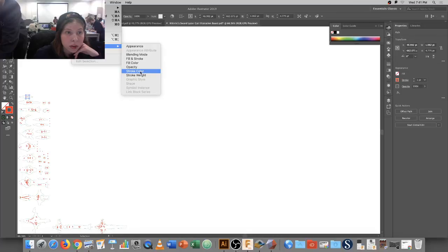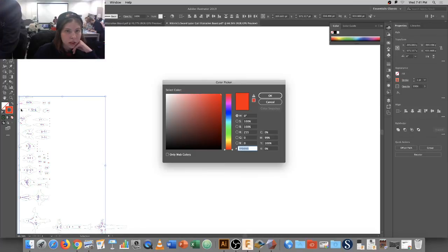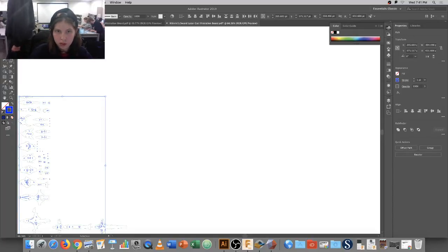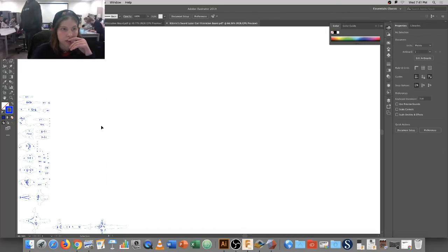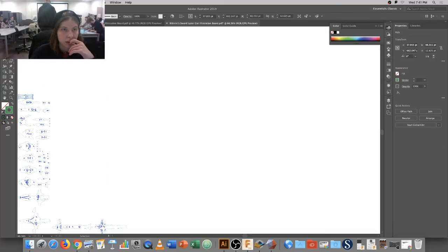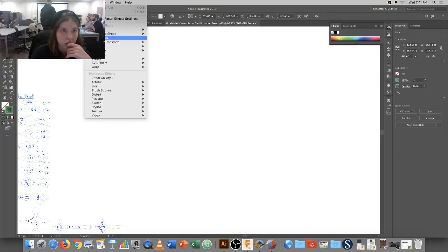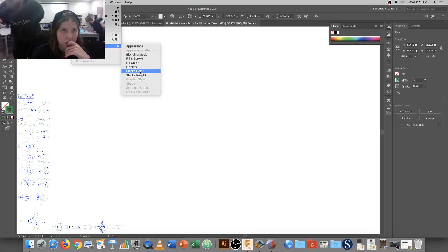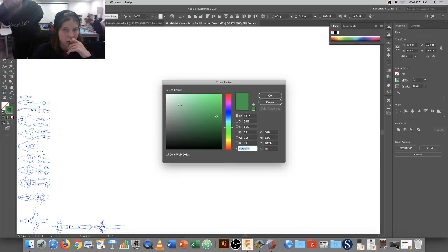Select same stroke color. So it's going to be blue 255. And I forget what the line weight is. Anybody remember what the line weight for the laser cutters is? 0.01. Thank you. So the line weight is 0.01. So for that, we put it to 0. Looking good.